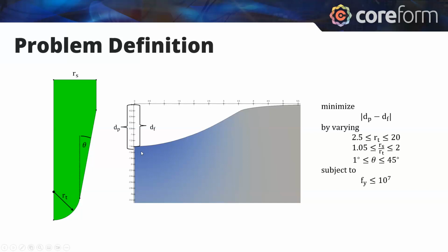What we're going to do with this nano indenter is depress into the target material 2 units down and then retract the nano indenter. We're shooting for a target where we'd like the permanent deformation to be at -1.5. So our objective function here is going to be the absolute distance, or do that as a square of the difference between the final displacement and the target displacement we had for the permanent deformation.